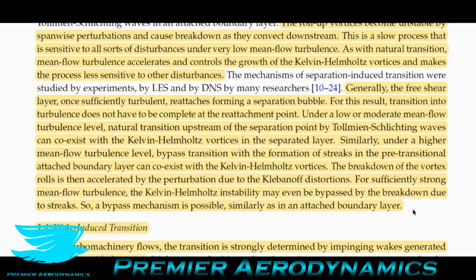Some people were saying that it only touches down and reattaches once it has transitioned. So as soon as it transitions to turbulence, that's when it reattaches. Other people were saying, well, it can transition later downstream once it's already reattached. But from my knowledge, it always has transitioned before it's reattached. So it's in that separated zone that the transition occurs. But anyway, let's move on.